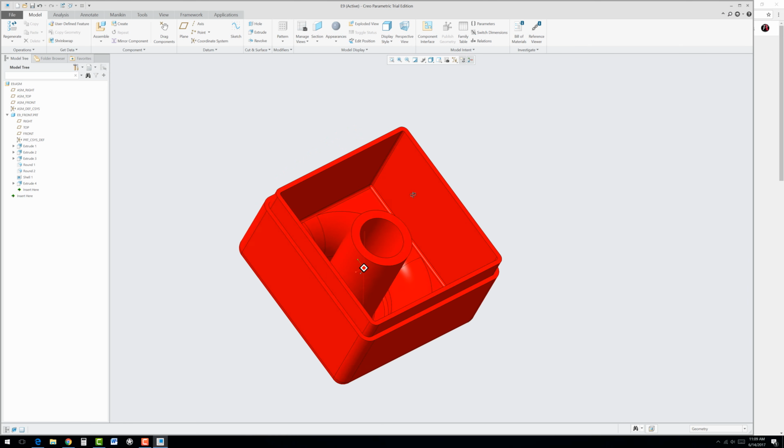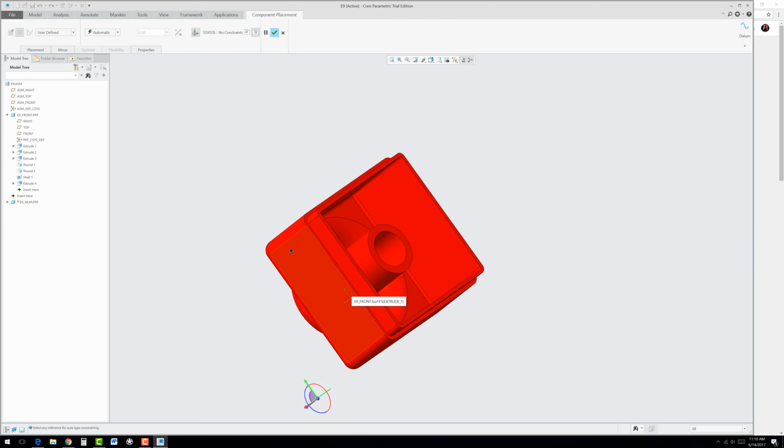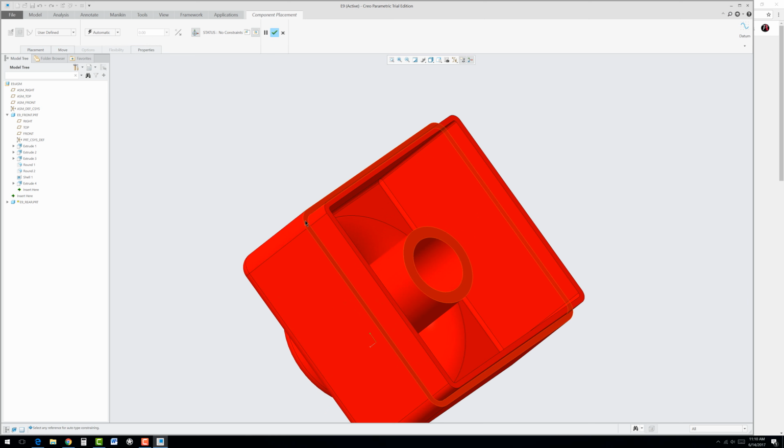Okay, so now we're going to go ahead and build something on the back side of this. So let's go back to Create, and over here again, Part Subassembly, and we're going to call this the E9_rear. Hit OK, and again, copy from existing, hit OK. And we could, in theory, go with the default. Or we could actually select this surface if we wanted to make sure we could draw on that. Either one is going to turn out, in this case, the same way.